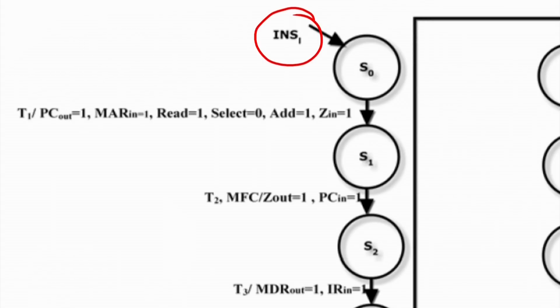Next I am going to go to state 1. So, what is the output? Initially state 0 is there. From state 0 to state 1, what happens? You should know that now I should be in state T1, that is from 0 the next state has come, that is the counter has now become 1. Then what are the outputs? If you remember, there is only one thing over here. After the initial state, you need not depend on any other input. The only thing is that state 1 corresponds to the fact that at present the instruction is INS1, that is add R1 M, register to memory.